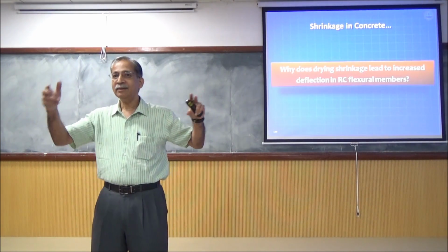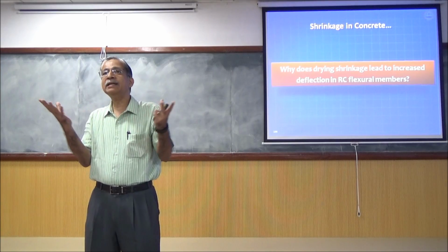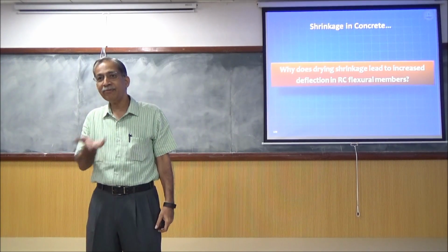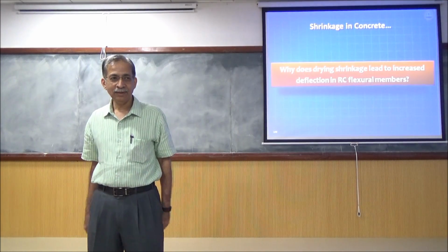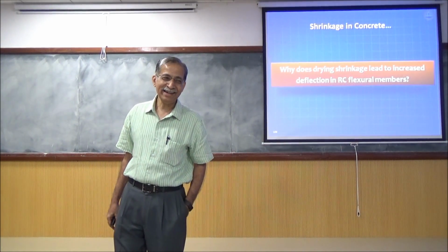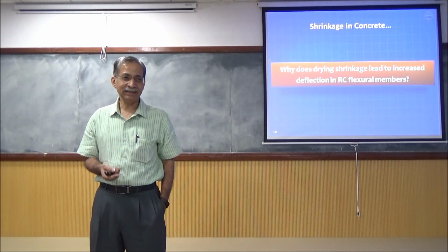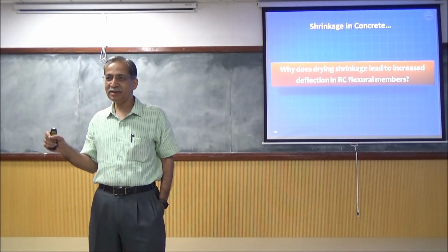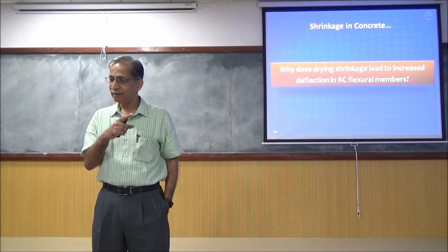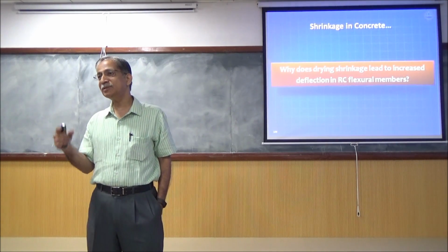Concrete is there. Volume shrinkage takes place. Let it shrink. What's the problem? Why will deflection increase? I decreases. How much will it decrease? You will find, if you work it out, the reduction in the I value is so insignificant. Even if you calculate, deflections are much, much more.